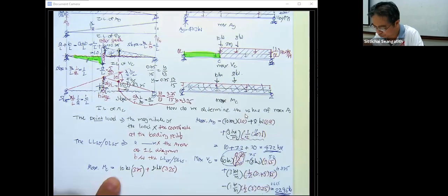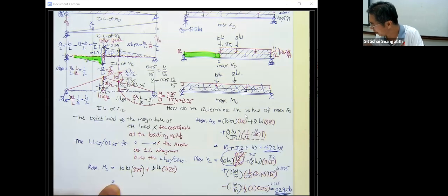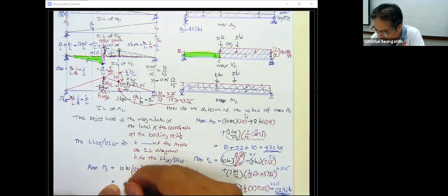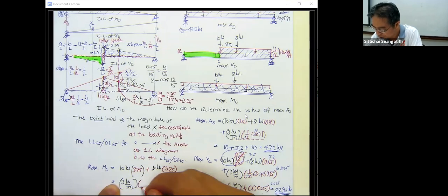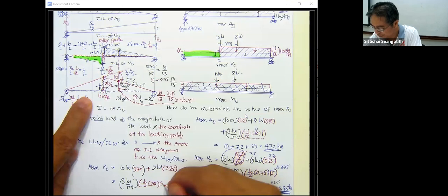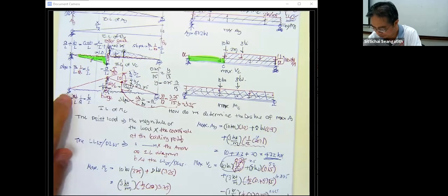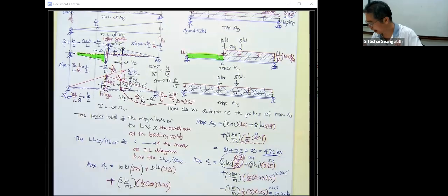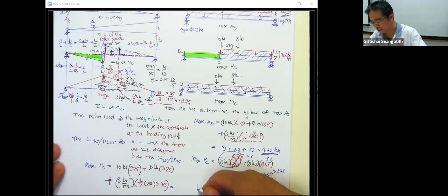And then next we have the force here. The combination of them is 3 kilonewton per meter, and then you times this by 1/2 of this one for 20, and this one for 3.75, and then you will get what we have. This is going to be plus, in the unit of kilonewton meter.